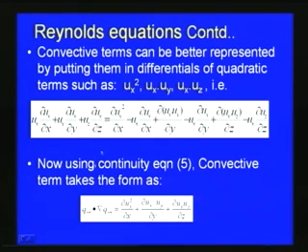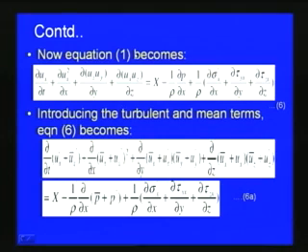And finally, the convective terms, which are represented in this equation as in the following, the convective term becomes del u x square by del x plus del u x u y by del y plus del u x into u z by del z. So, the convective terms in the Cauchy's general equation are transformed into this form by mathematical simplifications. Now finally, this Cauchy's equation or the equation of motion we can write in this form after changing the convective terms as in the previous slide.